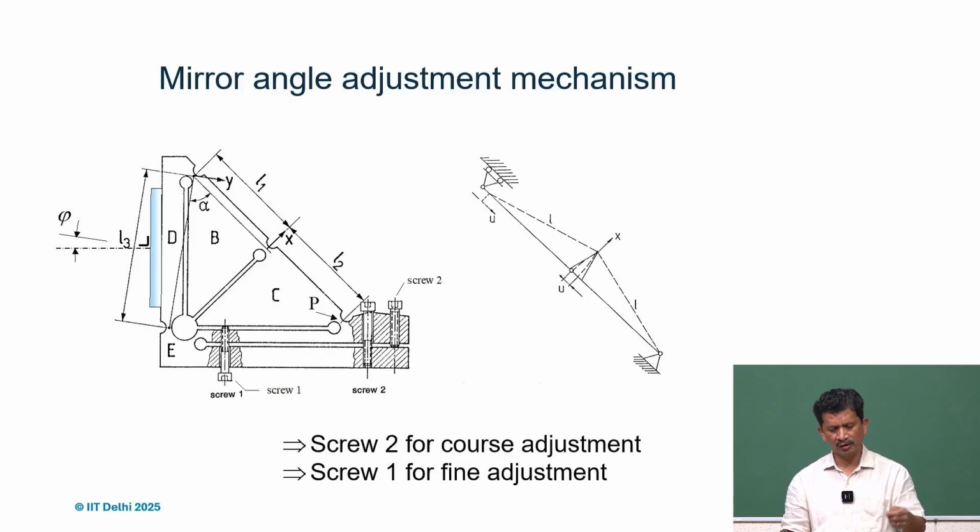And yes, here we are talking about adjustment with the screws. It's just to illustrate, but if it has to be done in a very dynamic way and at very high speed, then of course the screw can be replaced with some kind of actuators, piezo actuators, or any other kind of linear actuators, depending on the application, depending on the payload. So we'll talk about different case studies, different kinds of examples, and I think we should be able to appreciate the designs that we have here.